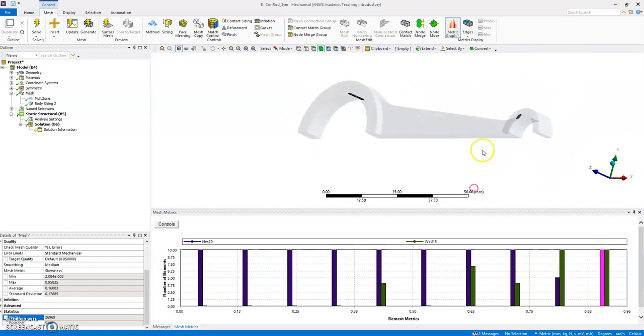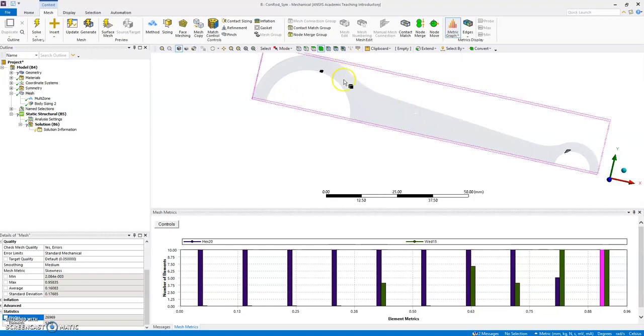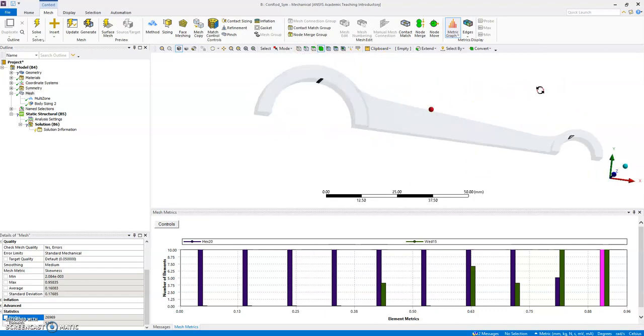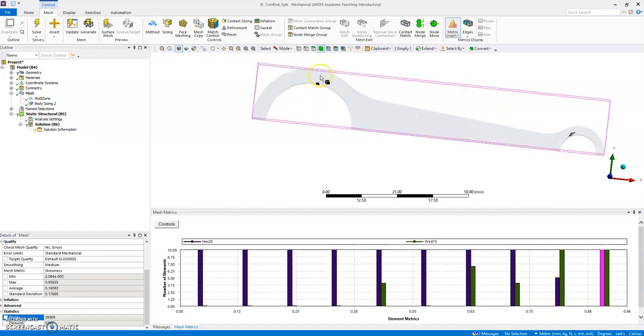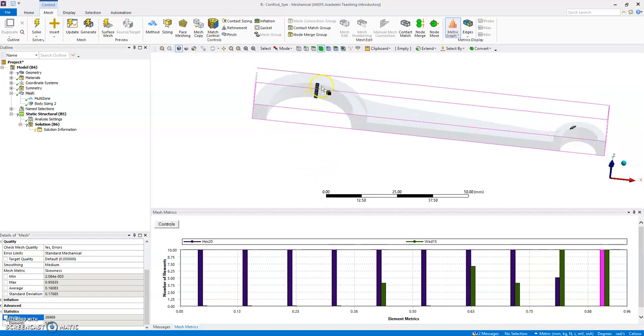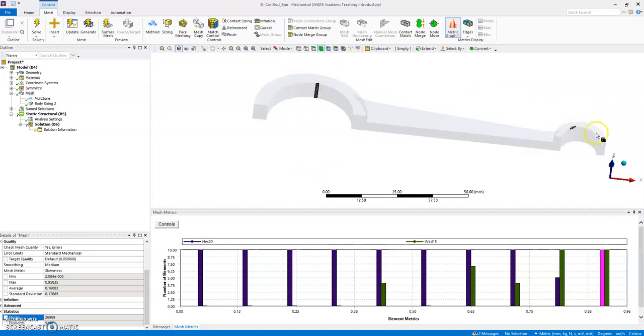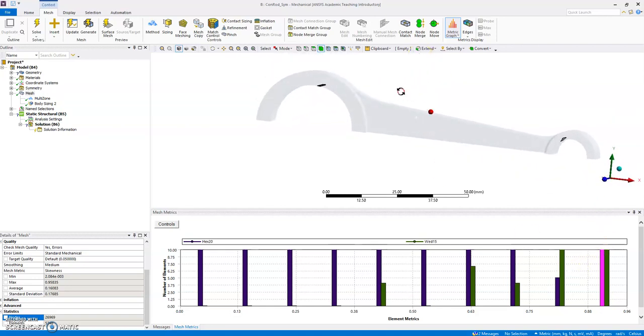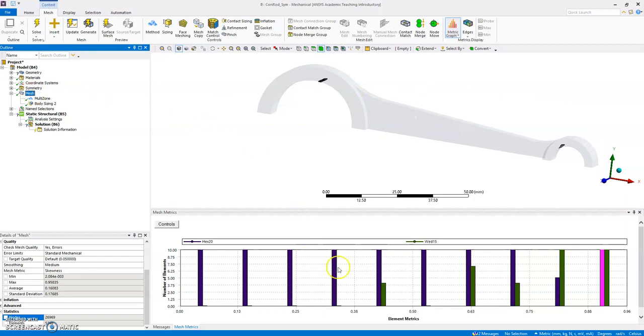But that's what we have to do. There could be an argument that we might want to remove that fillet as well. At the same time, interesting things might happen here. So at this stage, I would really need to do the simulation and check how far the areas of interest from stress are from the bad elements, and hopefully they won't contaminate the quality. Not hopeful. I expect some large stresses here and here. Another aspect that has been helpful is that by cutting it in 4, I can afford a decent mesh now. Well, decent-ish. I mean, I can do better.